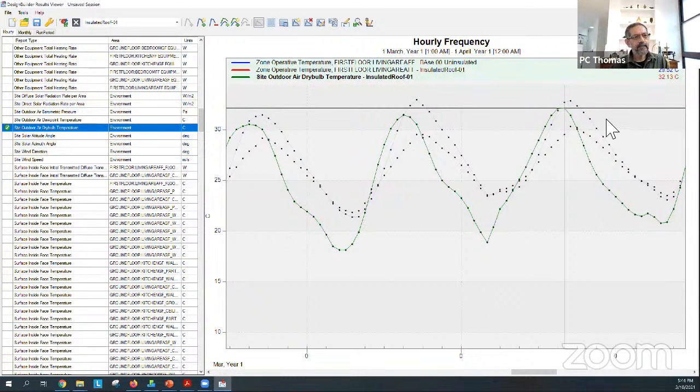But when I put insulation on the top of the roof, above the concrete slab, because then the slab acts like a moderating influence, you can see here it's come down to 29.3. So I got 3 degrees depression by doing this one energy efficiency initiative.